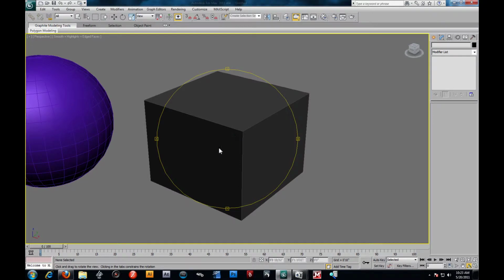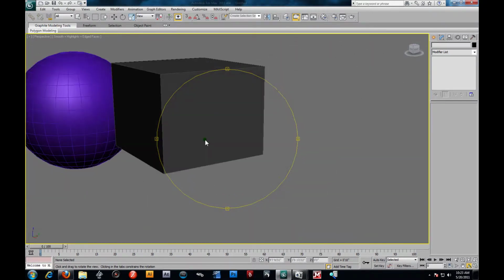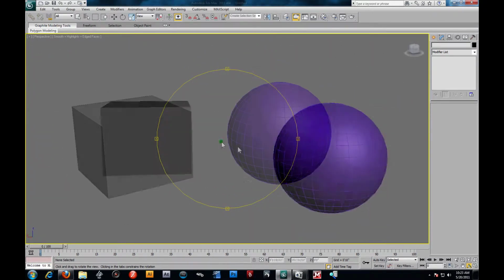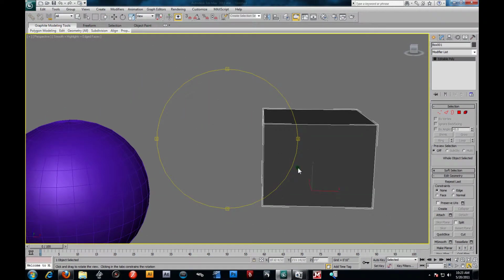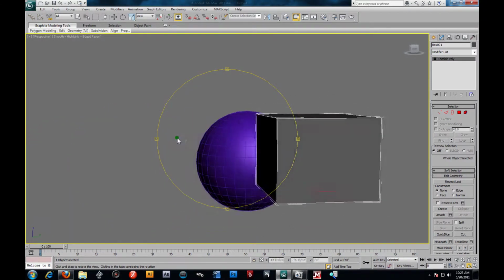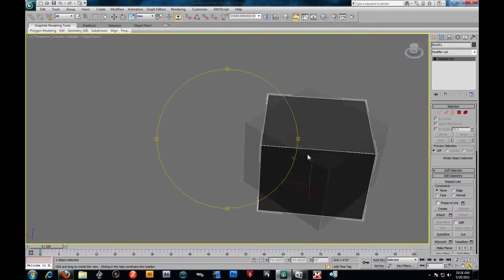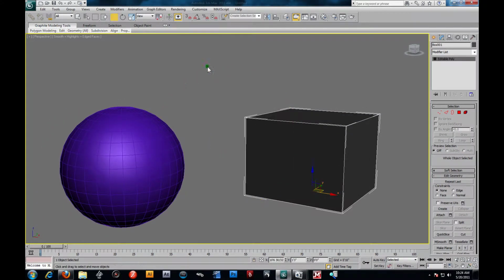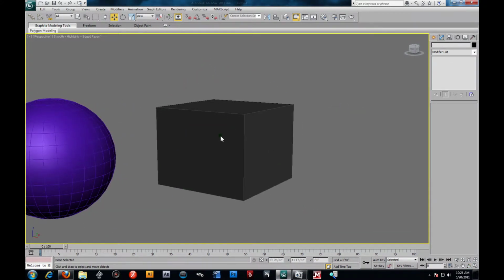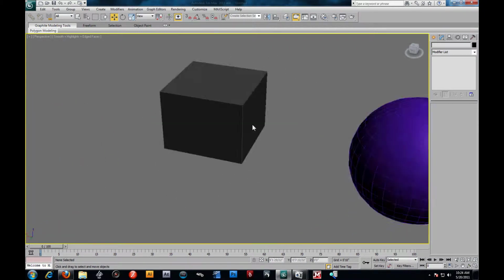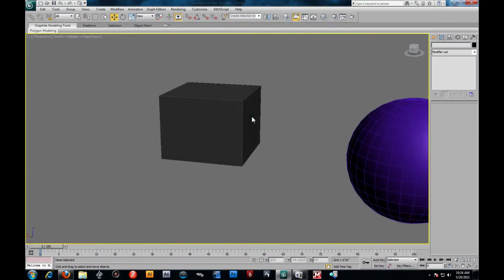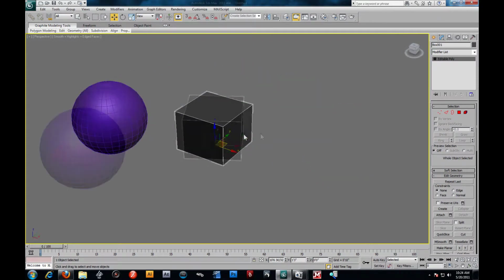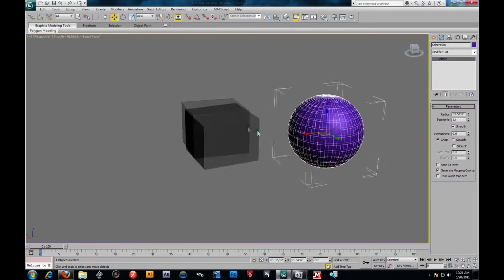That lets you know that you're orbiting around the world. You're not selecting a specific object. Or even if I was selecting the object and use that, I'm just rotating slightly around that object. The hotkey for that is if you hold down Alt and your middle mouse and move around, you start to orbit. Get used to using your Alt and middle mouse. So I'm selecting him, and I'm orbiting around him now. If I select the sphere, I'm orbiting around it now.